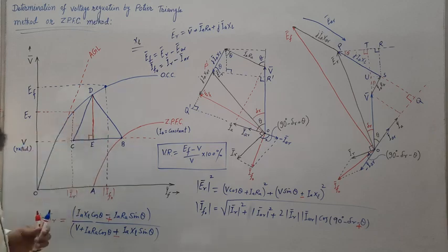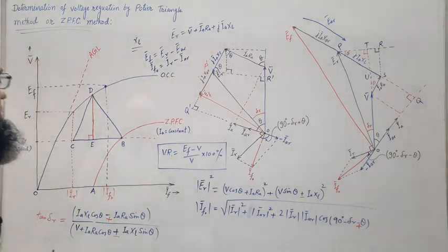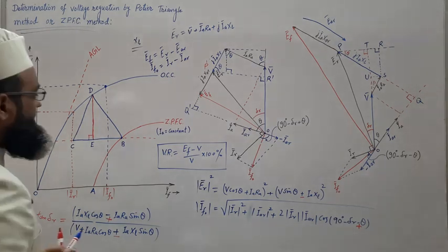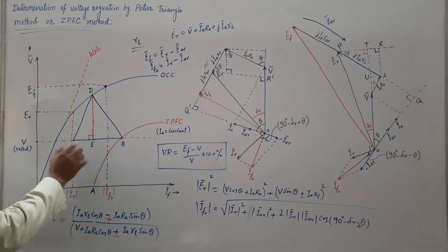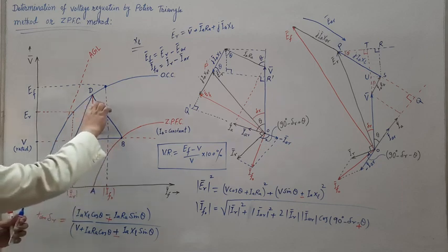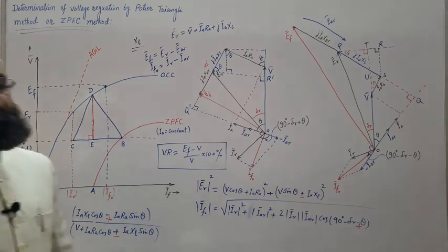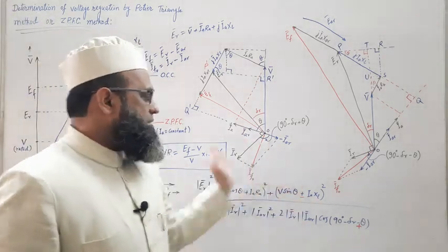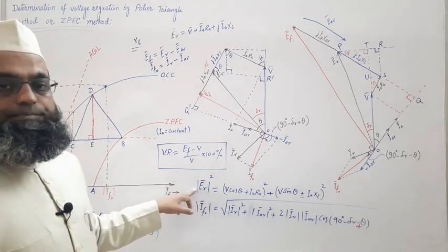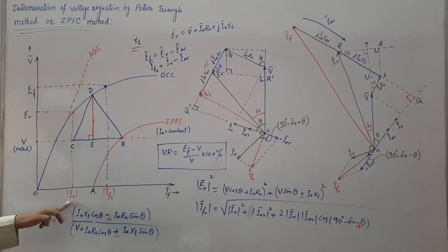This is field current required to overcome armature reaction drop. The second is leakage reactance drop, IXL. So from here we are getting XL. Once XL is known, substitute XL here, whether lagging or leading power factor, evaluate ER. Once ER is known, corresponding to ER, get IR.